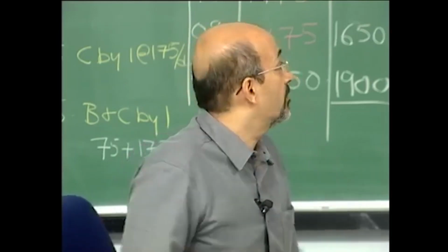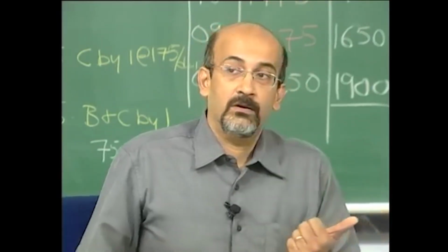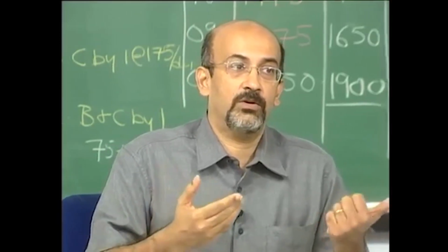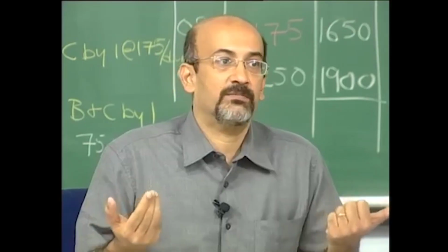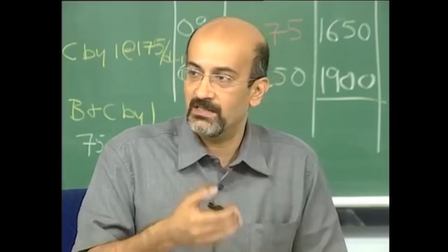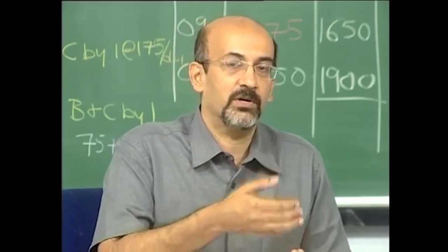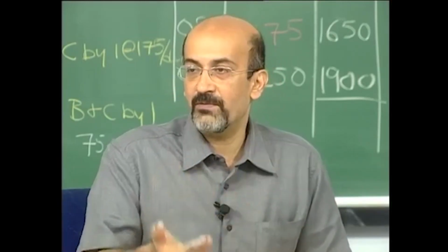Now what do you think is the relationship between project duration and, or let me ask you this way, what do you think is indirect cost and how does it vary with time on a project? Each day? Yeah, it would be constant. Each day I would expect to pay about the same indirect cost, because assuming my staffing levels are the same, my electricity usage is about the same, I have to pay for site establishment charges and all of this.